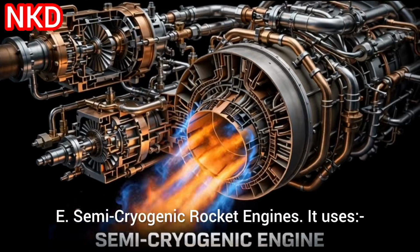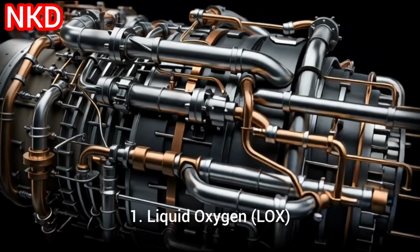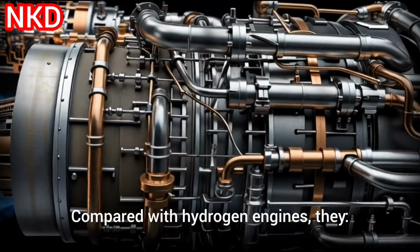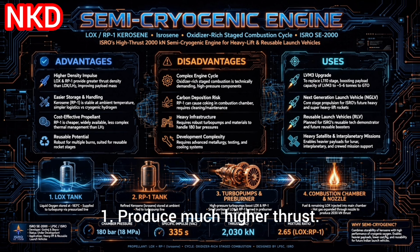E. Semi-cryogenic rocket engines. It uses 1. Liquid oxygen, LOX. 2. Refined kerosene, RP-1, or kerosene. Compared with hydrogen engines, they 1. Produce much higher thrust. 2. Are easier to handle. 3. Reduce launch costs. 4. Improve payload capacity.